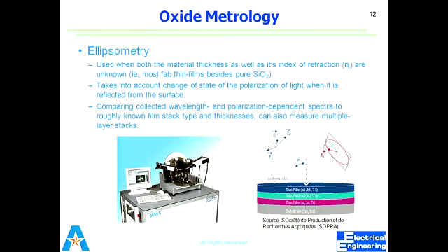Okay, so in ellipsometry, what happens? The phenomenon is actually the same: you have the wafer surface, and at a certain specific incident angle, which is fixed. In our case, it's 70 degrees in the ellipsometer that we are using in the lab. The light comes in, reflects from the surface of the oxide, and is detected by the detector on the other end.